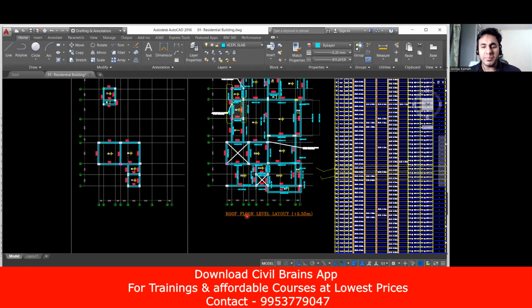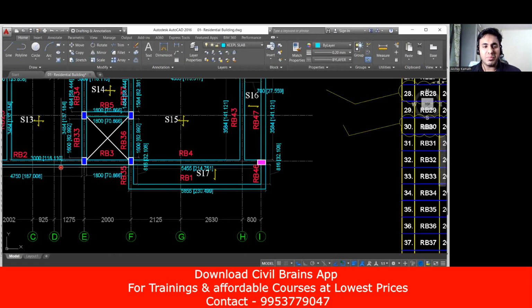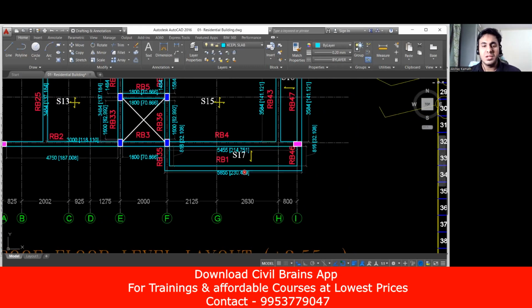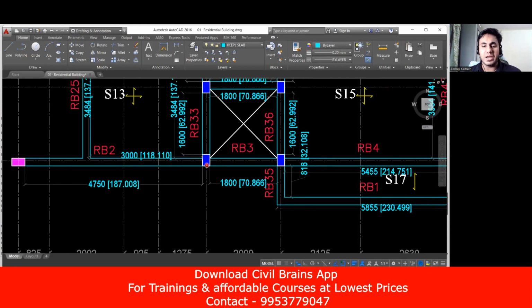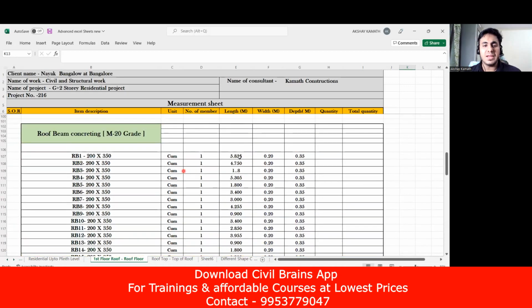So this is your RB1 layout. See here RB1, then we have RB2, RB3, RB4, and so on. You're getting my point. Then again, the same procedure: you want to find the length of this. In AutoCAD, I've taken the lengths and input all these values. Now RB2 is 4750, RB3 is 1800. So what I've done, if you see here, for RB1 that particular length is 5.855.